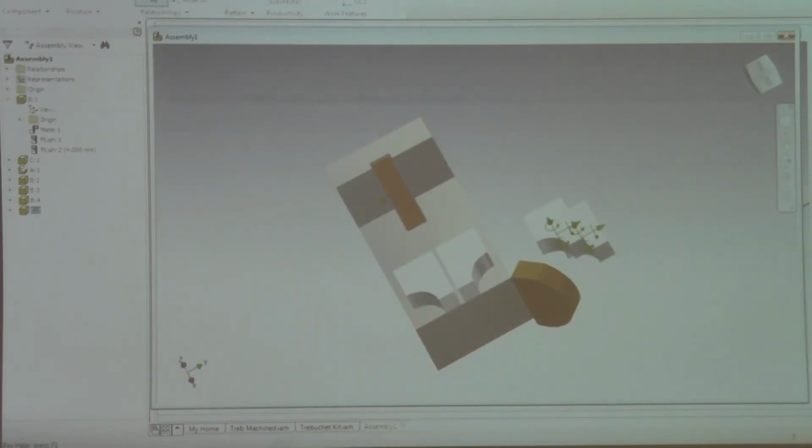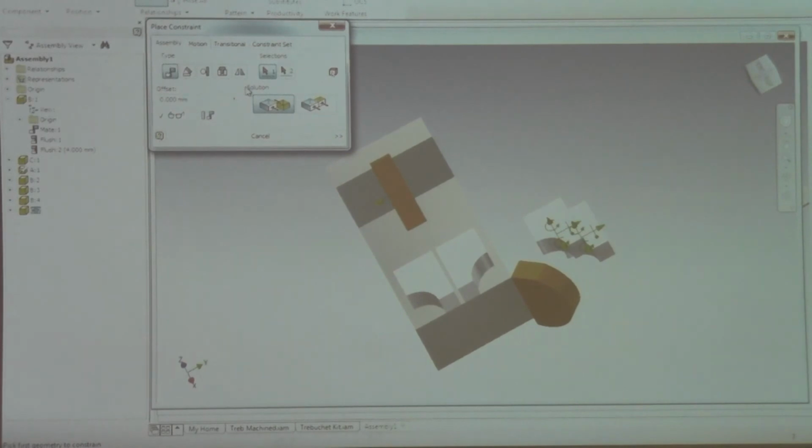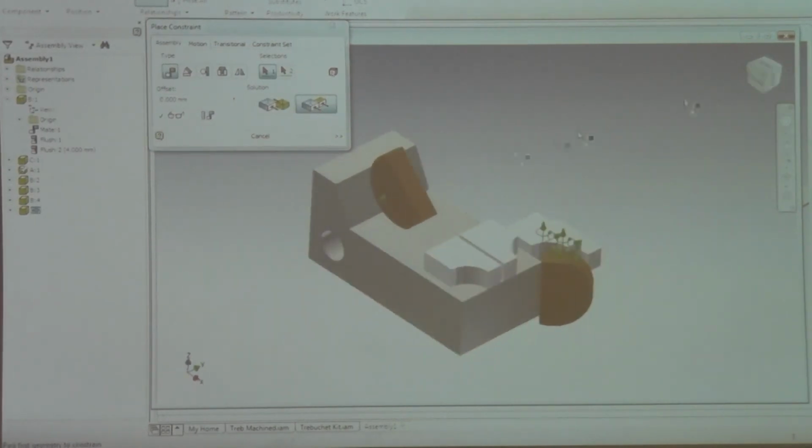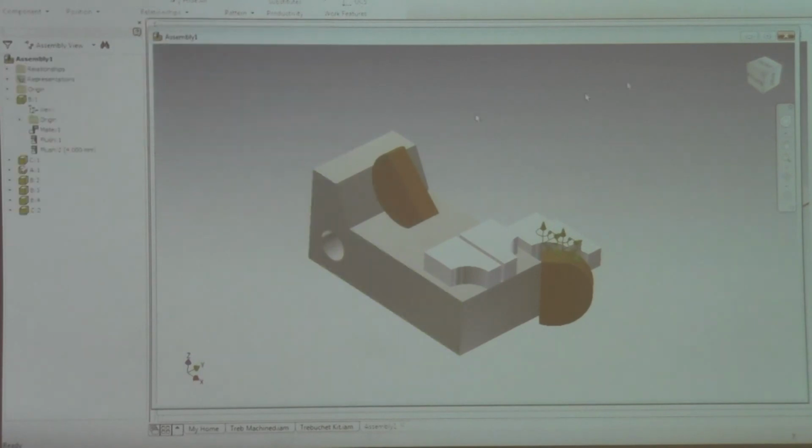I believe that I have a 20 unit flush constraint right there. So flush right there. Come over here, grab that side, it goes to 0. I change that back to 20, hit OK. All degrees of freedom are gone from that piece. From everything that I have touched so far, degrees of freedom are gone. That leaves these 2 pieces right here that I've already shown you how to do in a different location. Let's see you figure it out now.